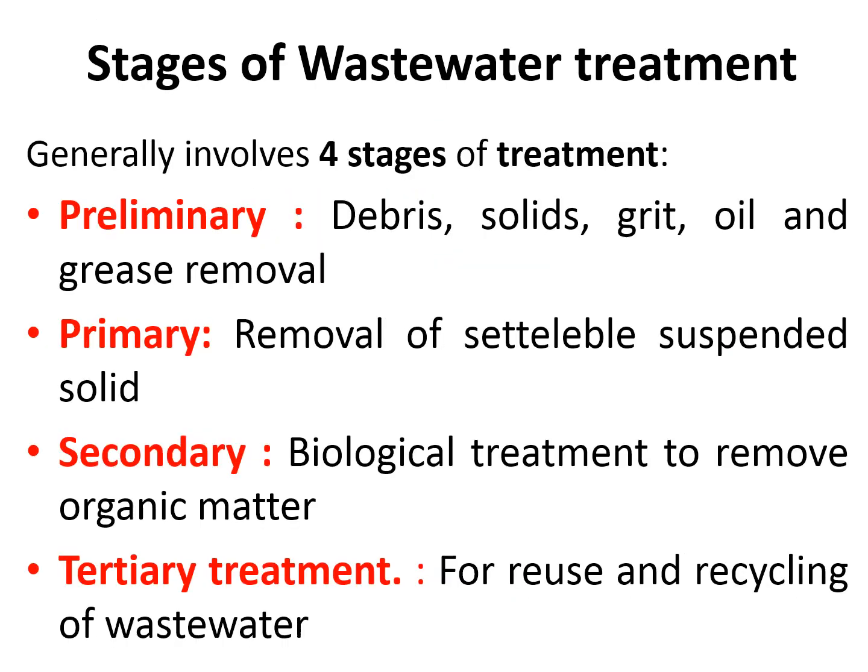Any conventional wastewater treatment plant generally has 4 different stages. The first stage is preliminary treatment. In the preliminary treatment, our main aim is the removal of debris, any suspended matter, grit, and oil and grease removal.